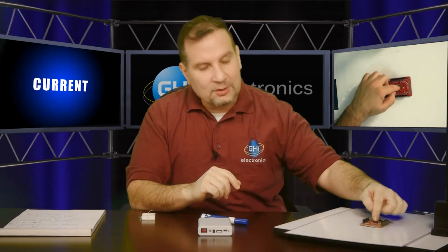So those pins on a microcontroller, they can give you 3.3 volts, but they cannot run a motor. They cannot run a large LED. They barely have enough current to run a small LED. So the current on a microcontroller is typically between, let's say, 5 and 10, 15 milliamps. The current is measured in amps.